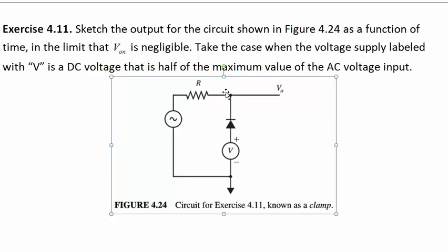So no current can go through this diode. That means the voltage that's here is also on this side of the resistor, and so we've just got this voltage repeated on the output. The extra voltage from the AC supply versus the DC supply, like it goes up to twice this voltage, would just appear across that diode. It's a reverse biased diode in that case.